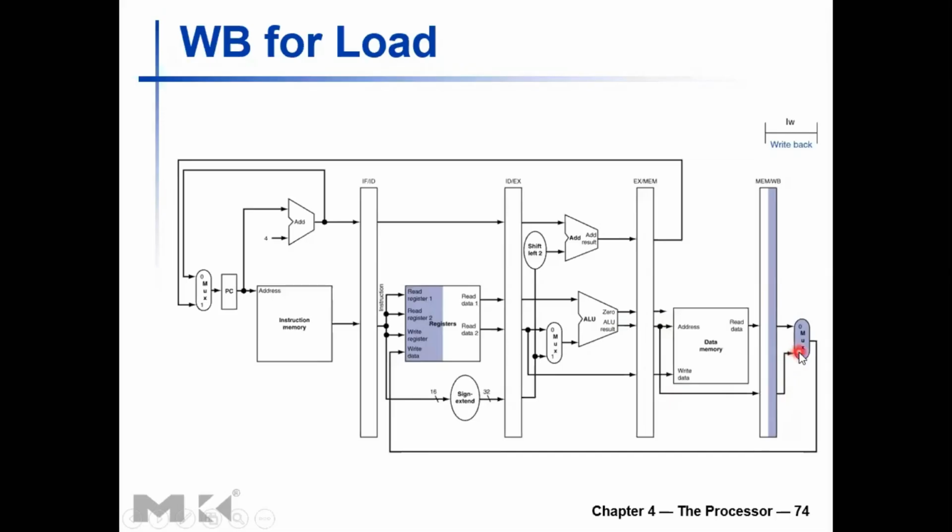So the control signal should have been preserved in the pipeline register, right? It should have been preserved through all these pipeline registers to make sure that if this is a load instruction, the value should have been 0, because you need to use the data memory output to write to the register file, right? So otherwise, if this was an arithmetic logic shift type instruction, you need the control signal to be 1 in order to let that signal go forward from there.